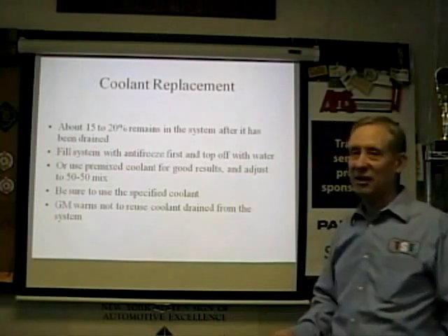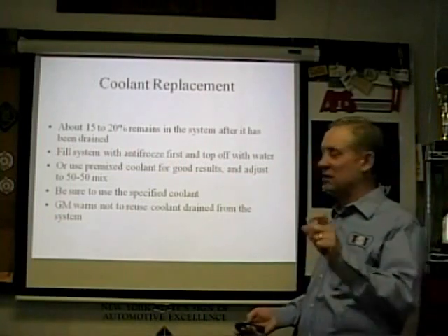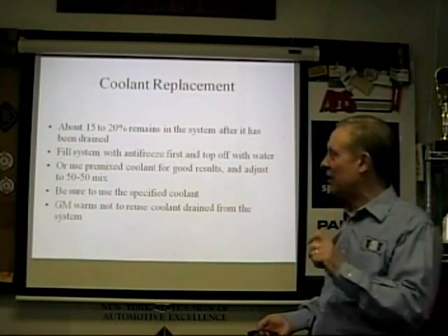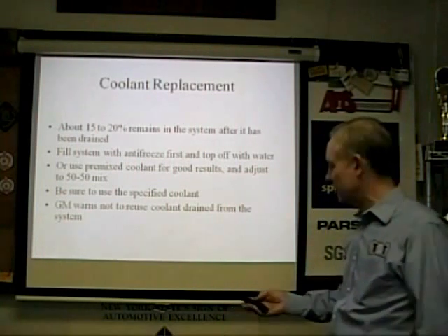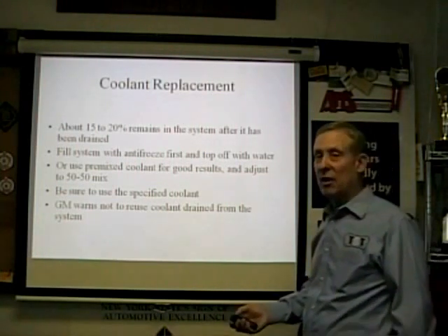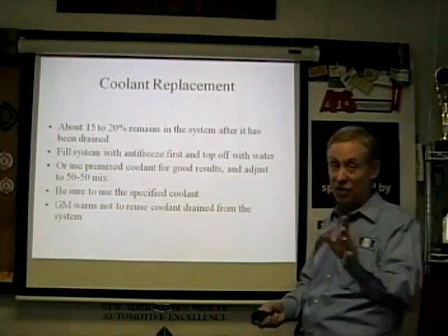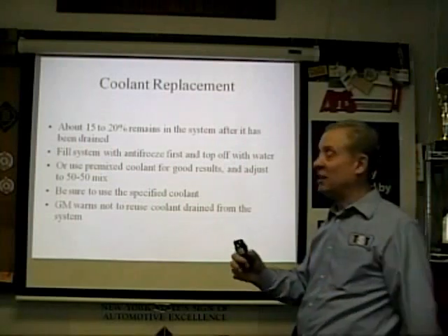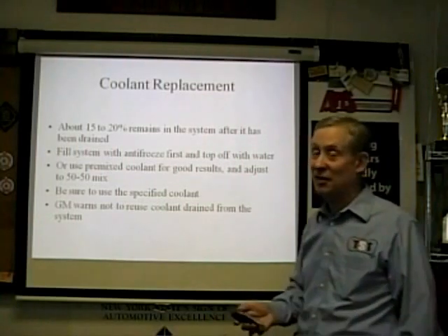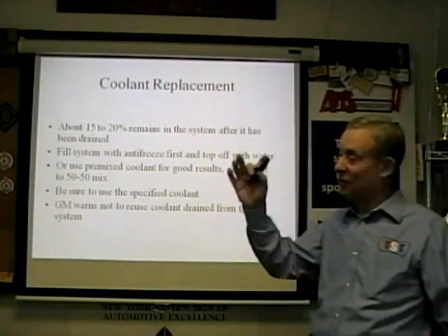And if I have to add a little, I'll add a little pure coolant, because 50-50 to 60-40 is the range that you want. The ideal range. Including your overflow bottle. Including the overflow bottle. And you have to then run it and purge any air or use an airlift. You have to make sure that it's clean. If it's a system that's resistant to that, you may have to take it for a good test drive up a steep hill or whatever it takes.